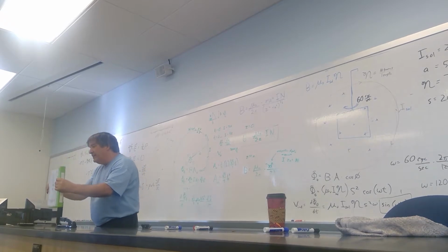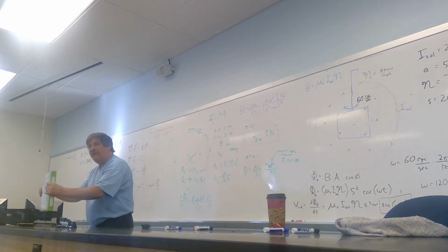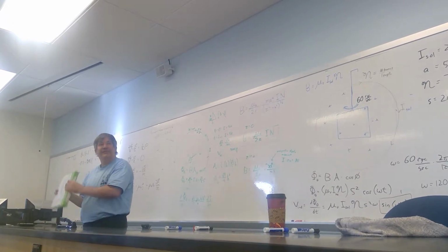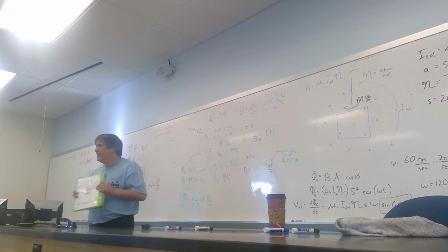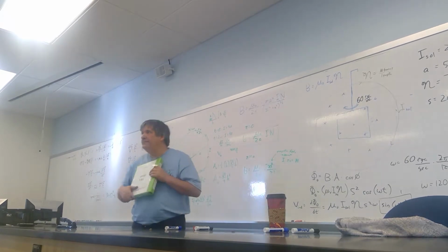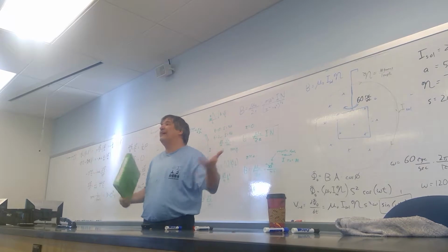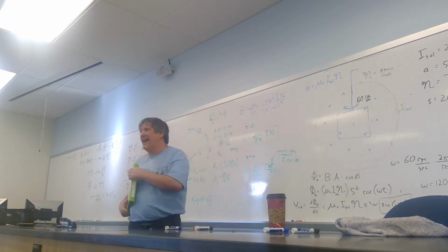And the current will continue to flow counterclockwise at that same value until this thing finally leaves the region, and then the induced voltage and the induced current once again drop to 0. Will be a square wave. Yes, the induced current and the induced voltage will be a square wave, exactly.